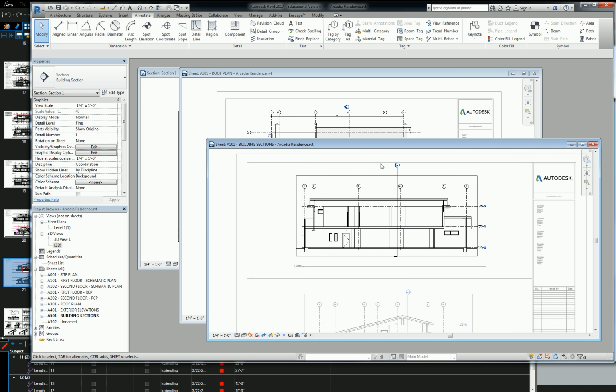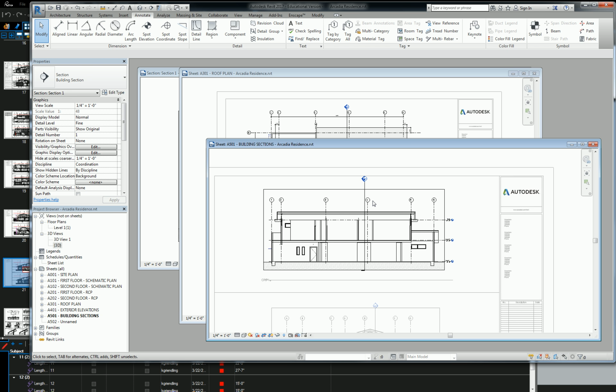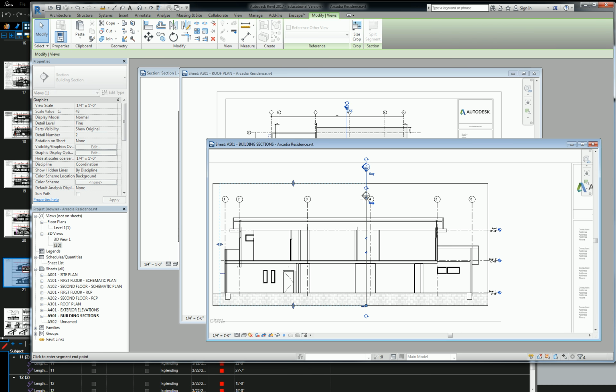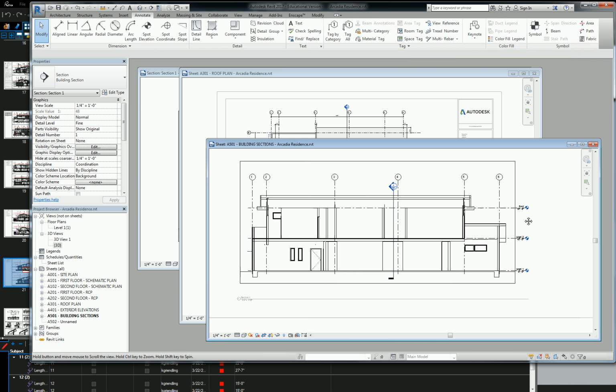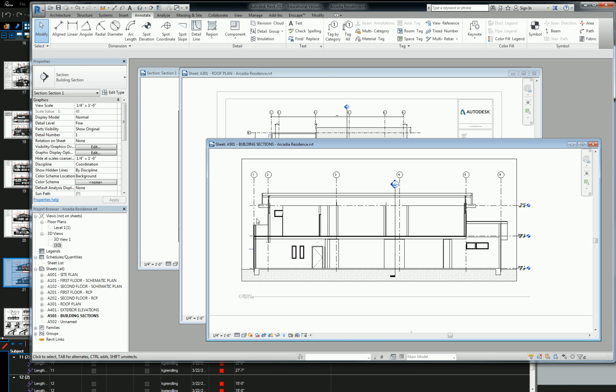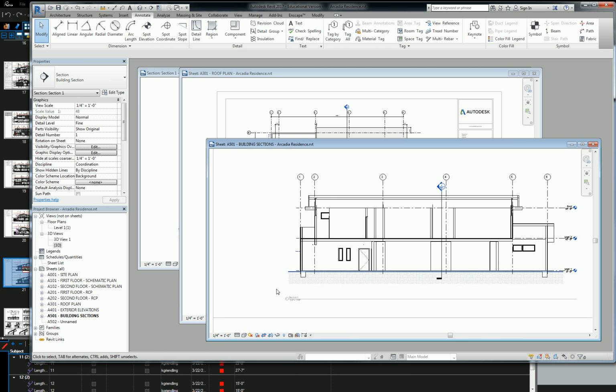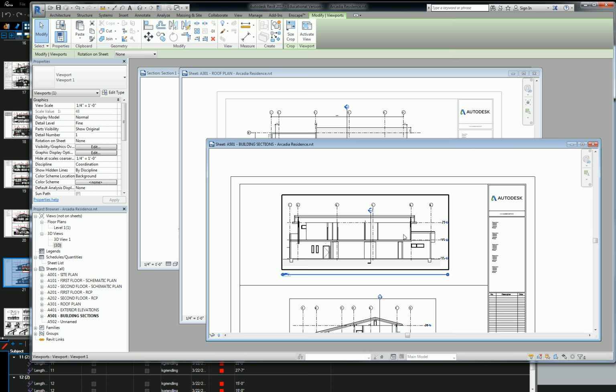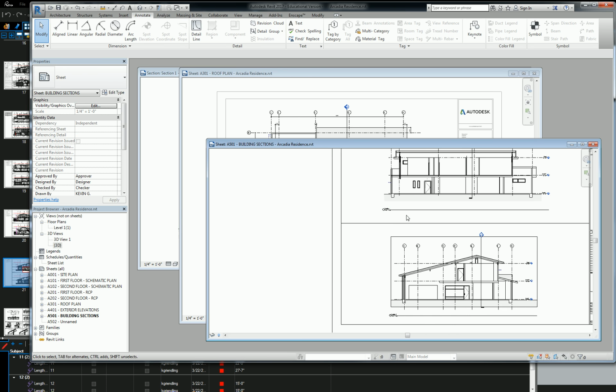The other thing that I think you guys need to calibrate is the sections that are crossing each other show up in each other's views. So you need to grab that element, and you can actually pull the section symbol down. And generally speaking, grids will go above any sort of sections and other symbols, just because they're a primary annotation. So I'm pulling that one in, and I think I'm going to turn off my crop region just because I don't need it. Yeah, something like that should be fine.